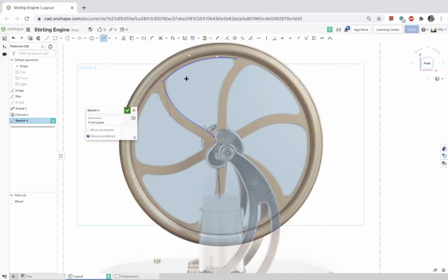So a spline is, you've got to be real careful because it likes to grab stuff. It's real sticky. It's a third order equation. Third order equation means there's two inflections. The maximum you can do with a spline is an S because it's a third order curve. If you need it to do more than that, you must use multiple nodes.